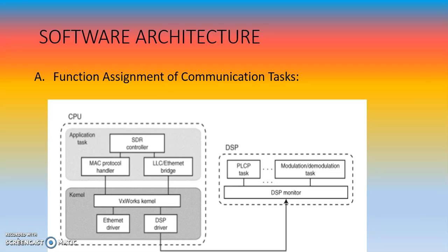The above figure shows the software configuration of the prototype in WLAN mode. We use VxWorks here because the WLAN protocol has far stricter requirements in terms of interrupt response time than PHS, and this real-time OS also allows optimization of the function assignment. Our previous SDR prototype used Solaris and was unable to achieve adequate inter-process communication. So VxWorks offers significantly shorter interrupt times and allows finer allocation of tasks.